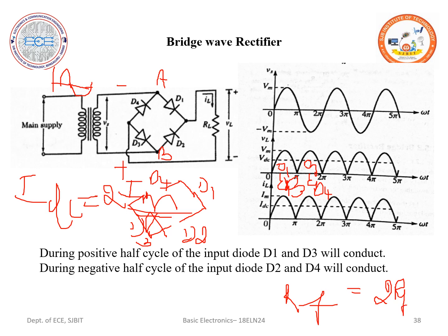So the same steps hold good, but the only variation is that we substitute wherever we find RF with 2RF, right? So when we come to the efficiency, the very same efficiency is going to provide you 81%. And similarly, when we come to the ripple factor, gamma is equal to 0.40.